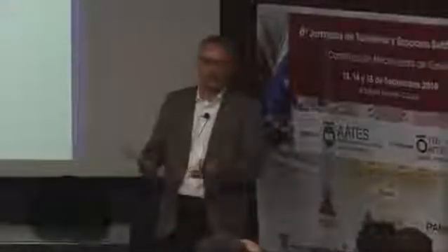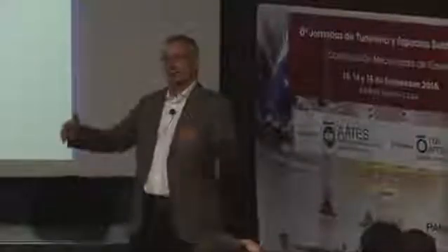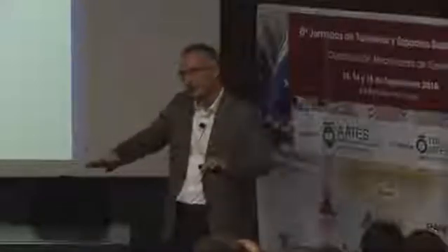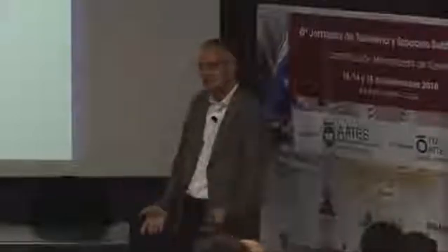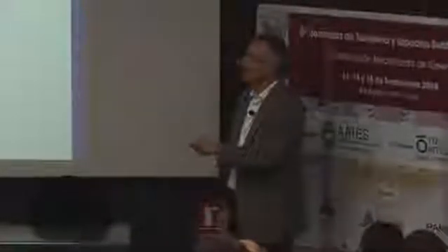If you stop for any reason with the TBM advance, stop the cutter head, of course the material has time to segregate. So the heavier excavated material settles down, and your foam and especially the air just comes up to the top, and so you increasingly create an air bubble.